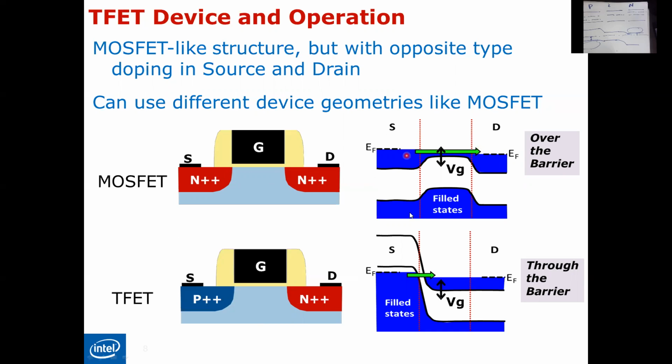I believe we already spent a lot of time in understanding this, and here is the energy band diagram for the tunneling field effect transistor. As you can see, my dear students, the Fermi level is now inside the valence band and inside the conduction band. If you remember, we already studied this case and we called it a degenerate semiconductor material.